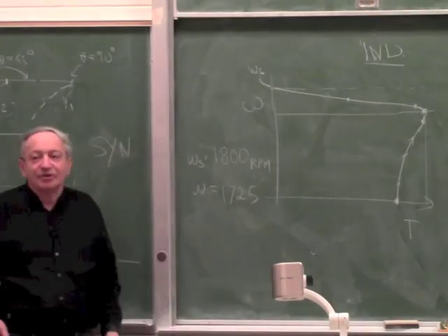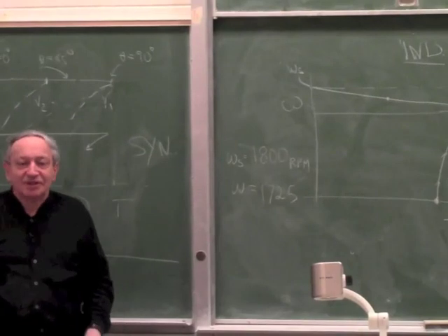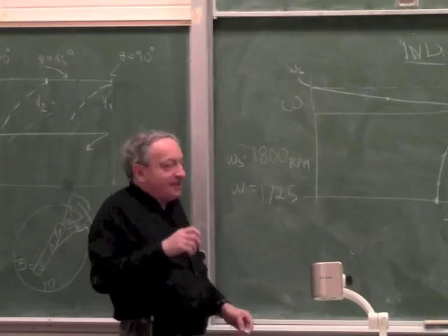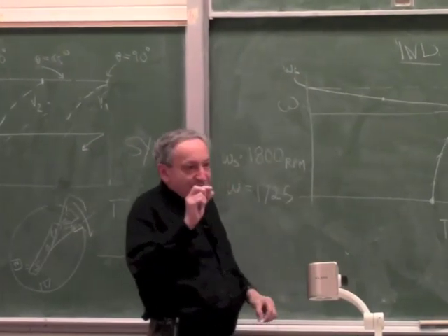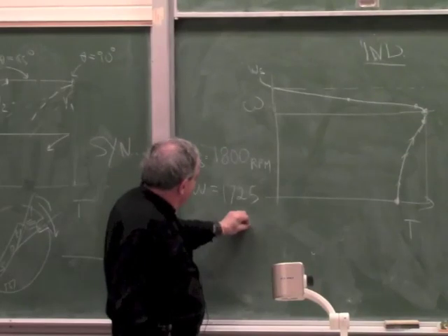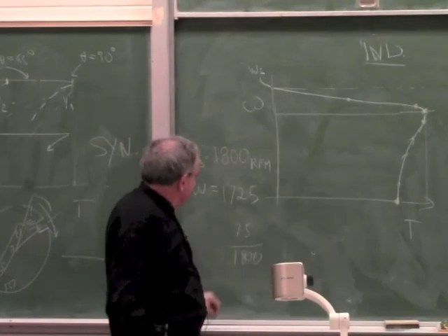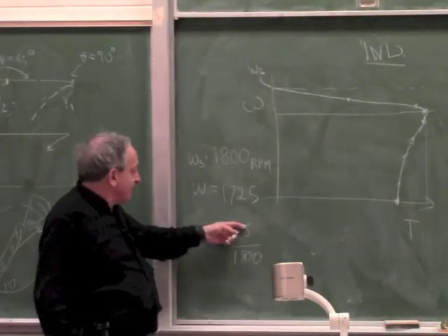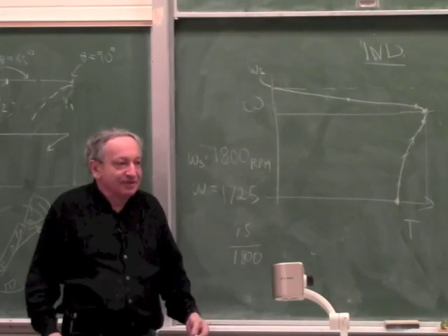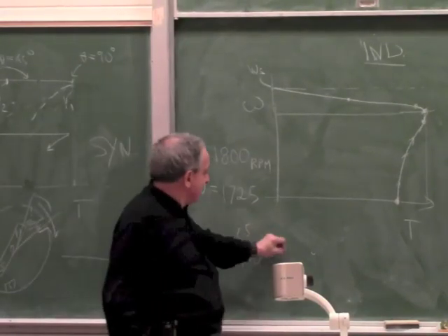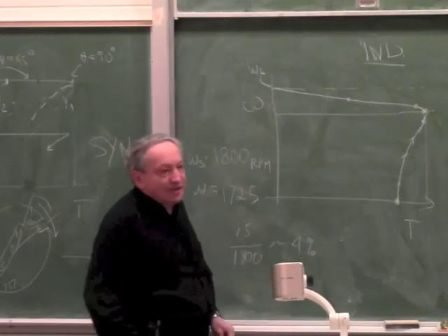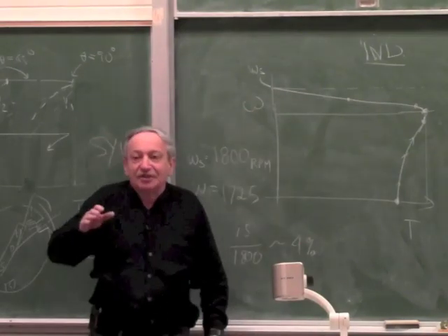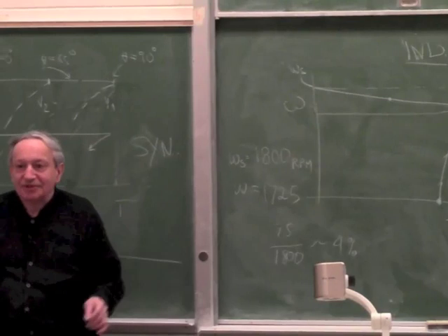That's a standard motor in your furnace, in your washing machine, and all the stuff at home, except your table saw. So what we're talking about is the slip frequency. We're talking about 75 out of 1800, which we said is roughly 5%. If it was 90 out of 1800, it would have been 5%. Let's say 4%. So in round numbers, it's a constant speed motor. It runs at 96% of synchronous speed, which is close enough.